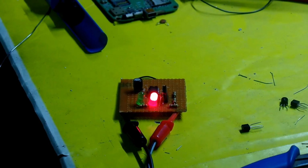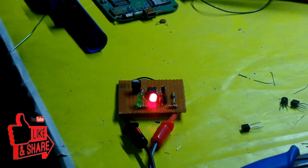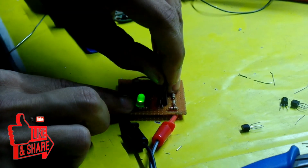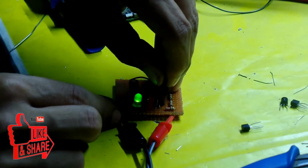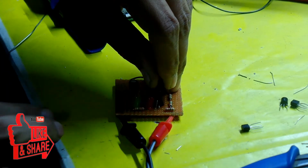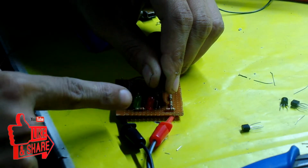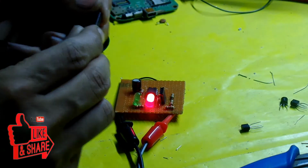By the way, this transistor was good, but this was a Darlington pair transistor, which does not work with these circuits, which are maybe low power. I didn't check for the pinout or anything else. Now here I got the big transistor, B877 I think, or maybe B377. It's a PNP, so we see the red light is blinking, which means that the PNP transistor is okay.